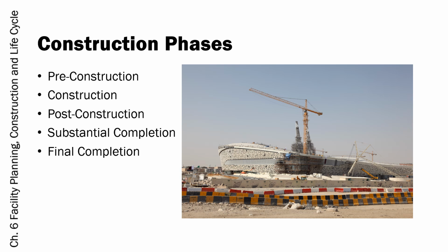The various phases and milestones of a construction project all have their own set of activities and objectives. In the pre-construction phase, this phase involves all the planning, design, and coordination that must occur before actual construction begins. Some key activities during this phase include finalizing the design and obtaining necessary permits and approvals, establishing the budget, timeline, and procurement process, selecting the contractor and other key personnel, preparing construction documents, and ensuring that all stakeholders are aligned on the same scope and objectives.